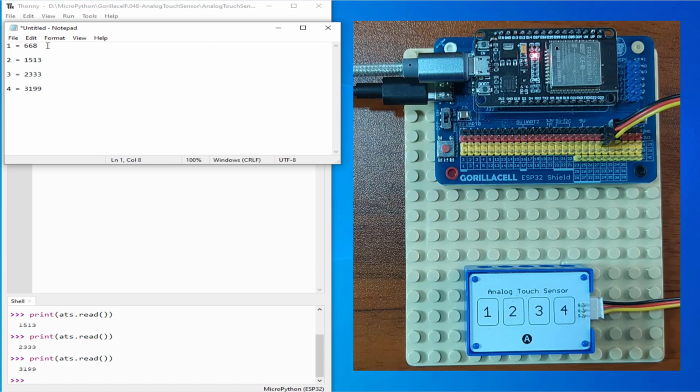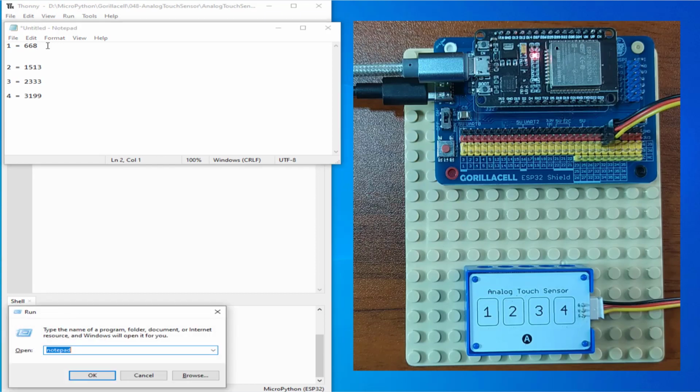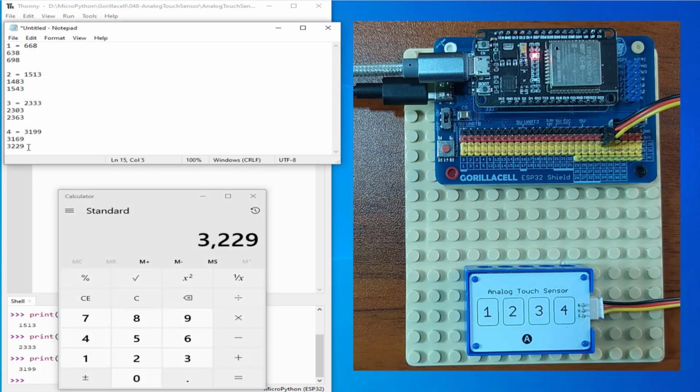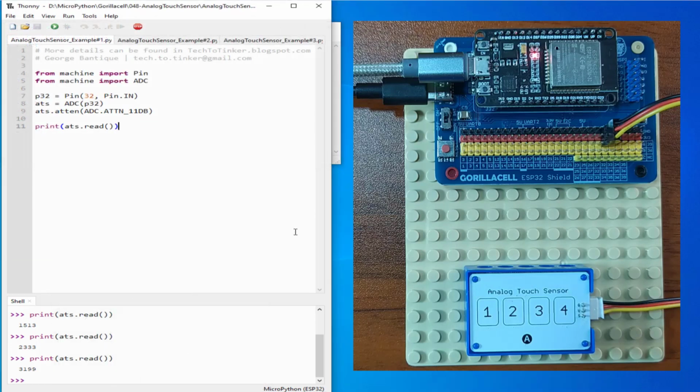Analog values tend to change from time to time, and we need to catch each touch sensor touch event. To do that, we need to check for a lower and upper limit value. For this lesson, I will use ±30. Now let's briefly discuss example number 1.